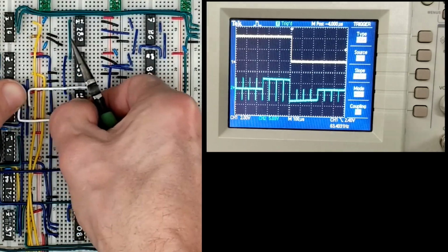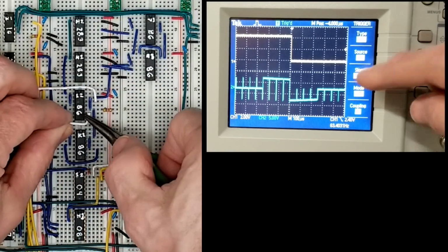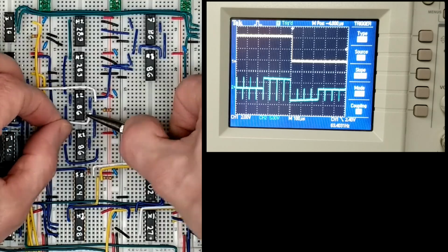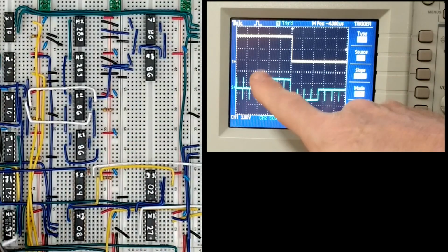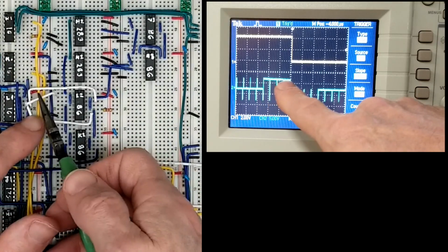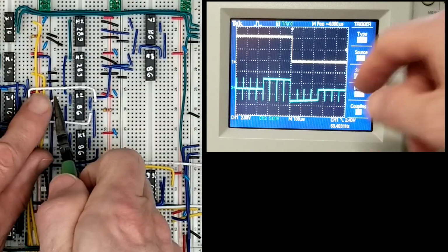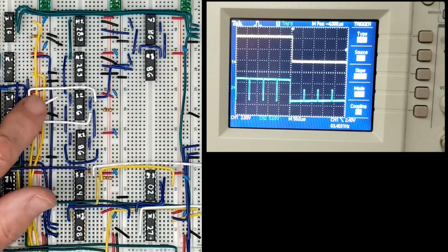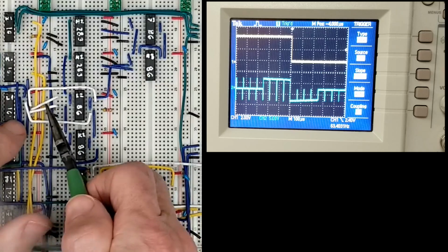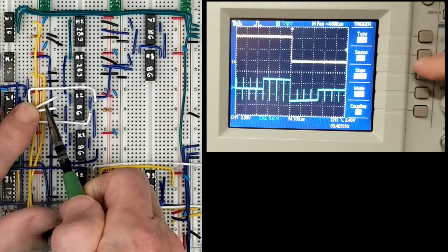Let's take a look at this on the scope. I'll first trigger on the fall of VSync. You can clearly see the left boundary just before VSync drops. The side boundaries use 4 whole vertical lines, so the video signal is high for all pixels during the entire last 4 horizontal periods.